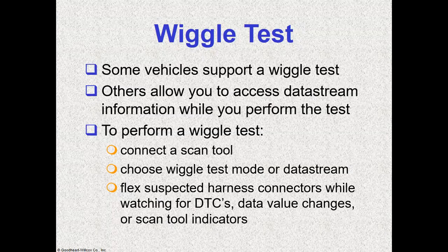Once we do live data stream, the computer goes in that mode and focuses on that particular sensor. So once we wiggle the wire, any slight change in reading will trigger the code. We have a lot of sensor wires running in that harness, and once we wiggle test it, any value change from any one of the sensors will trigger the code. So you can fish out that sensor in that particular way.